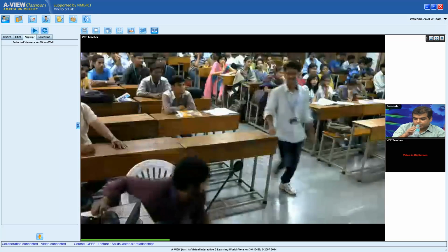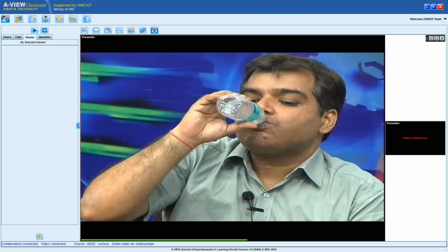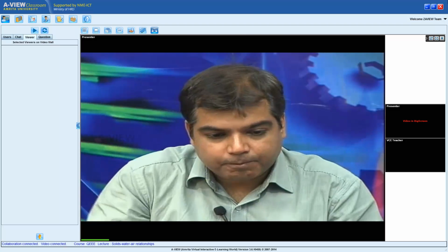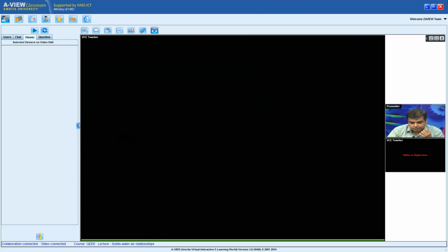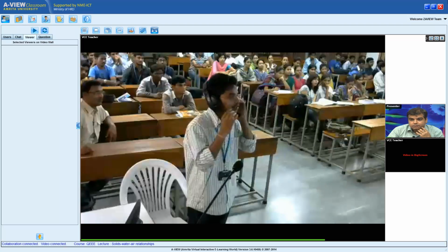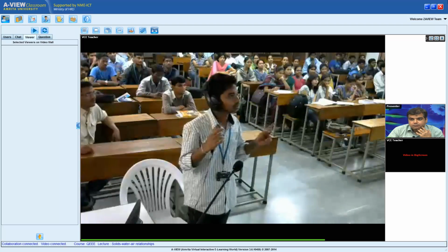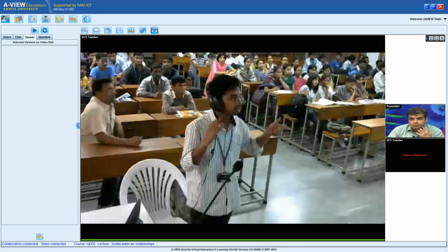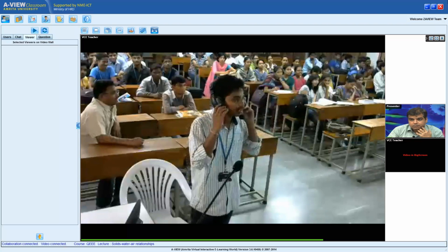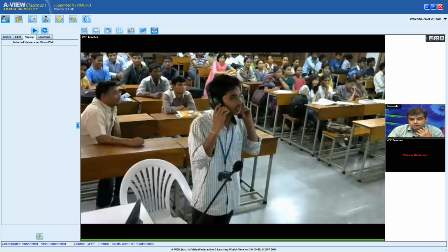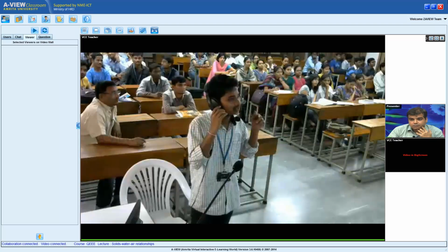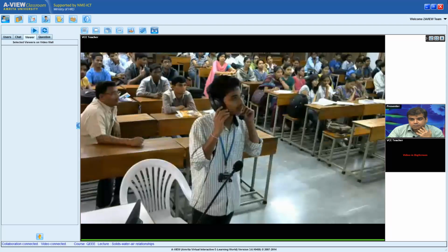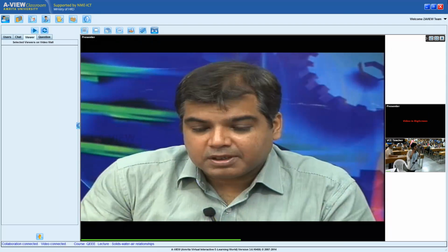Any other question, please? Sir, for finding the liquid limit in Casagrande, we are plotting the graph between number of blows versus water content. But in case of cone penetrometer, we are taking the coordinate in the x coordinate, sir. Why don't we take a similar graph there? Well, it would not matter.